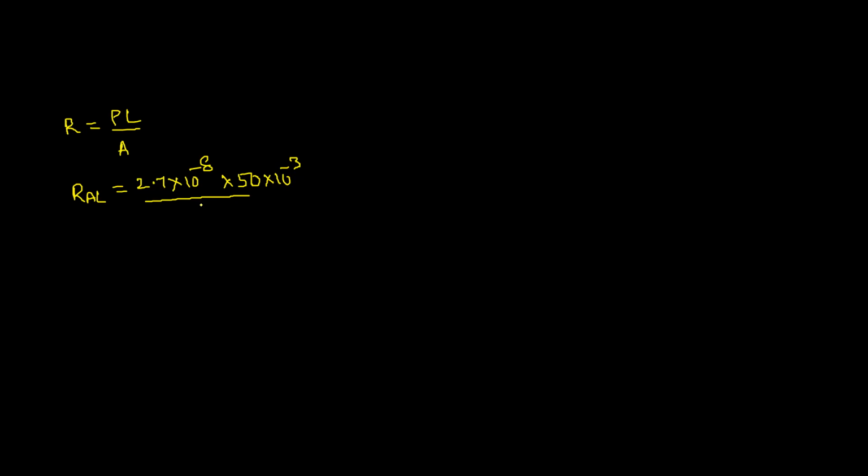Square cross section is area equal to a square. Given now 7 mm, 7 mm. So I'm taking 7 square minus, and that is now given 2. So 2 square, mm square means 10 power minus 6. See carefully, in rho L by A, while taking A, from total area subtract area of the iron. Okay, this is now resistance of aluminum.